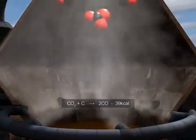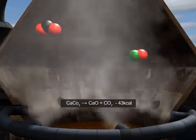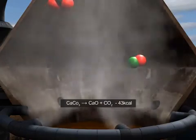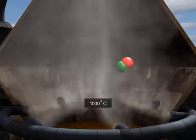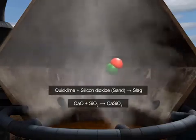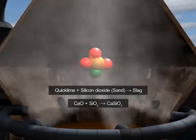At the same time, the heat causes the limestone present in the charge to decompose and form quicklime and carbon dioxide. The reduction of carbon dioxide and the decomposition of limestone are endothermic reactions. Owing to this, the temperature of this region falls to about 1000 degrees Celsius. Calcium oxide or quicklime fuses with impurities such as silicon dioxide to form liquid calcium silicate or molten slag.